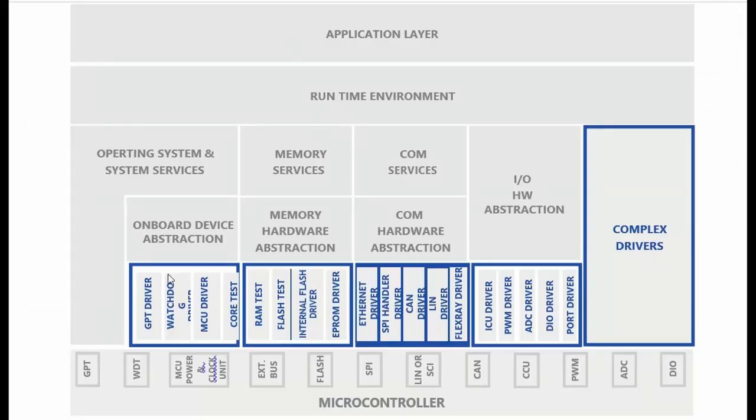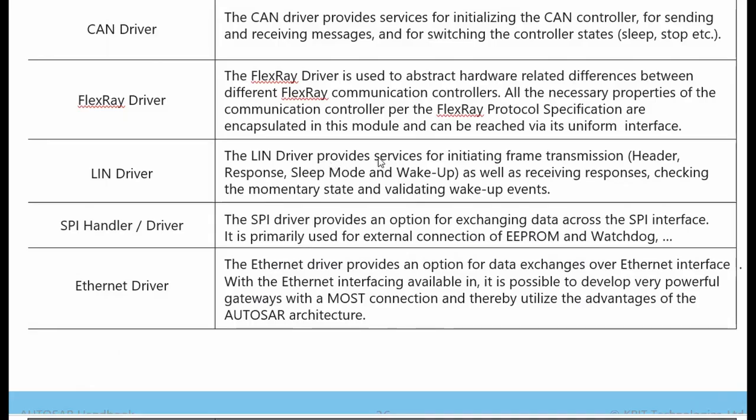Then finally we have MCAL, the microcontroller abstraction layer. Here we have the CAN driver, LIN driver, FlexRay driver, SPI handler, Ethernet driver, EEPROM, watchdog manager, MCU drivers. Every driver related thing will be present in this area. You just need to know these kinds of things.